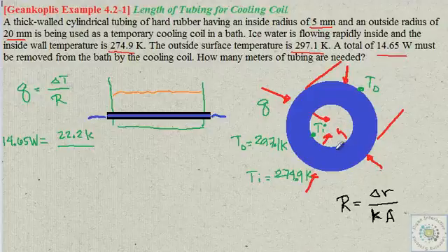In this case, when we say area here, since heat flows through a variable area, at the outer surface there is quite a lot of surface, but as the heat flows inward, the area where it flows becomes smaller and smaller. In that case, we mean the log mean area.